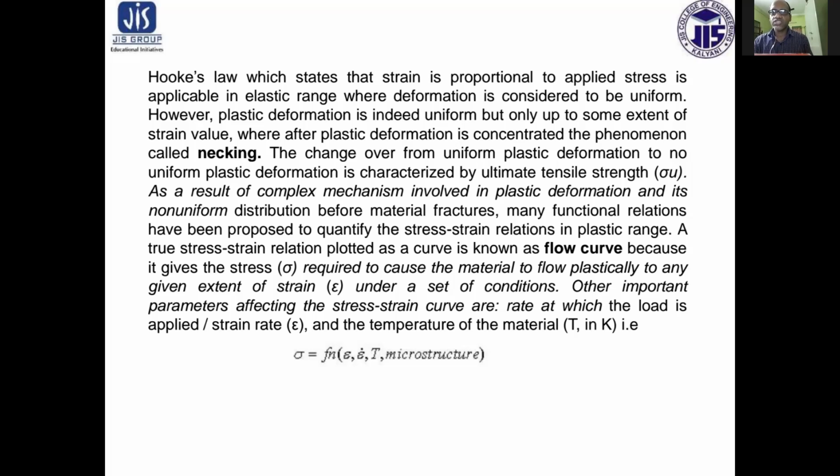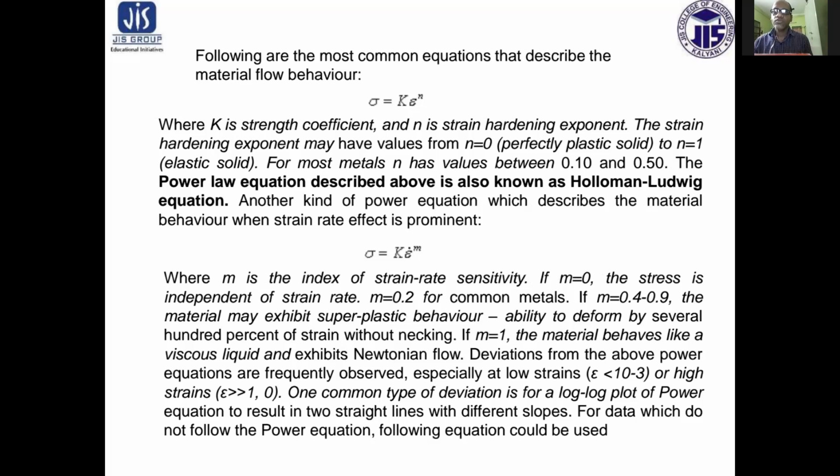A true stress-strain relation plotted as a curve is known as a flow curve because it gives the stress required to cause the material to flow plastically to any extent of strain under a set of conditions. Other important parameters affecting the stress-strain curve are the rate at which the load is applied and the temperature of the material. That is, stress is a function of strain, strain rate, temperature and microstructure. So following are the most common equations that describe the material flow behavior.